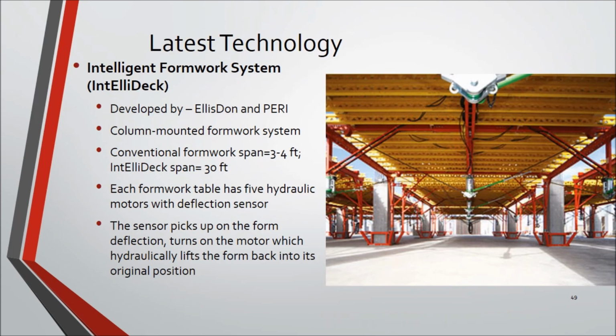The third one is quite interesting. It is an intelligent formwork system or IntelliDeck. It was developed by Ellis-Don and Perry. It is column-mounted formwork system such that each formwork table has 5 hydraulic motors with deflection sensor. The sensor picks up on the form deflection, turns on the motor which hydraulically lifts the form back into its original position.